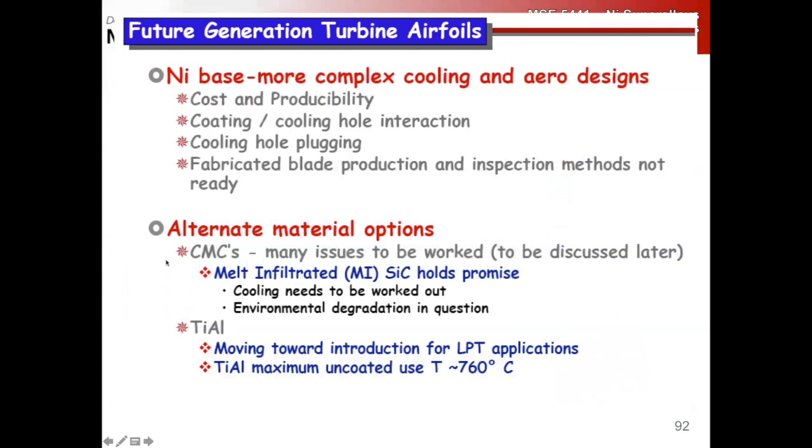So, alternates. I think my personal feeling is ceramic matrix composites, right? Oddly enough, these are silicon carbide composites, which sounds weird, but you take fibers of silicon carbide and then do a melt infusion. So you have silicon carbide fibers and a silicon carbide matrix. Silicon carbide has about 1,000 crystal structures, right? If you look at the phase diagram of it, it's really complicated.